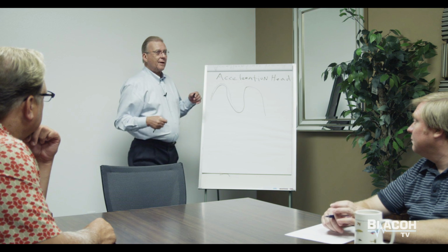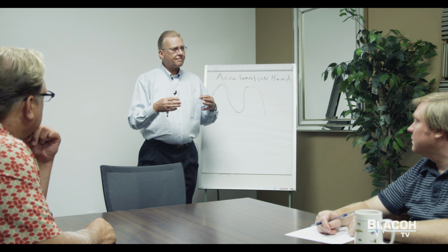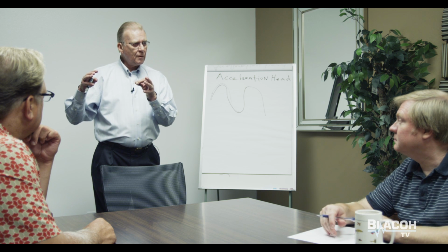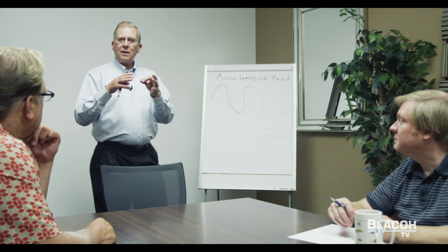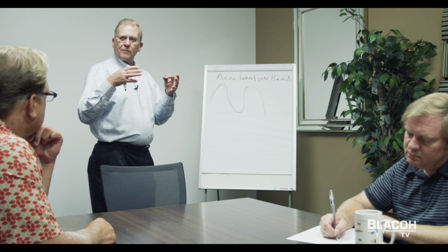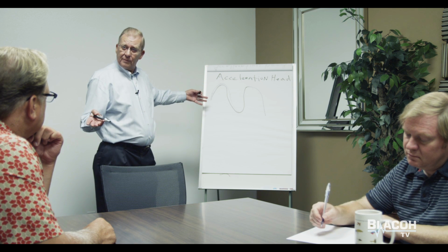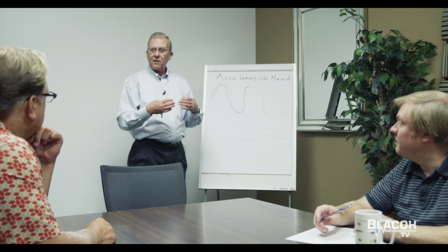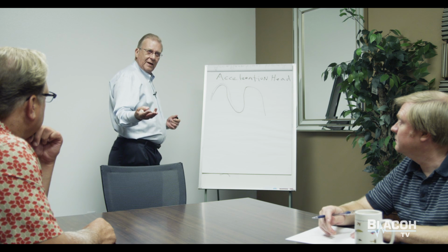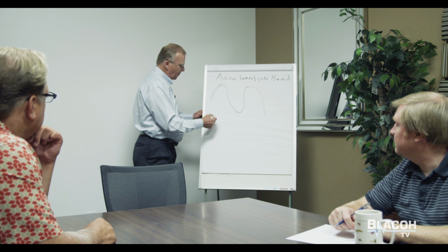But with a reciprocating pump, that flow is not constant. So if you try to use those pressure loss charts that are published, it would not relate at all to the energy required or the loss due to friction created by a reciprocating pump, right? Because we are starting and stopping the flow just like going through town. So if you take a pulsation dampener and put it at the discharge of the pump,